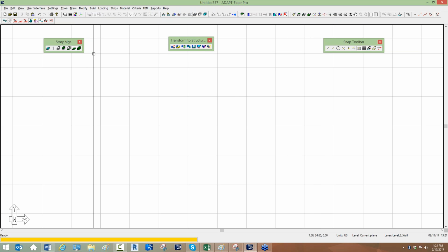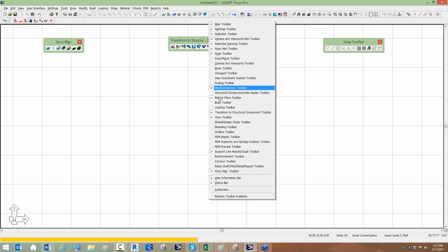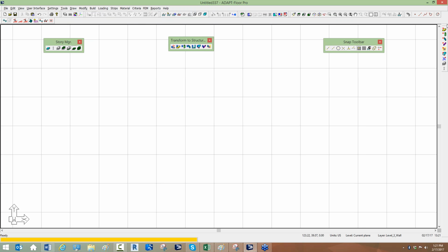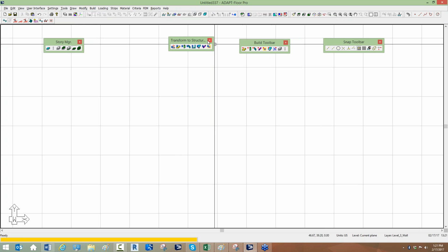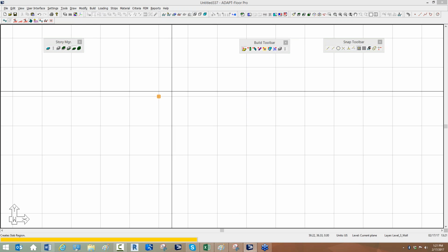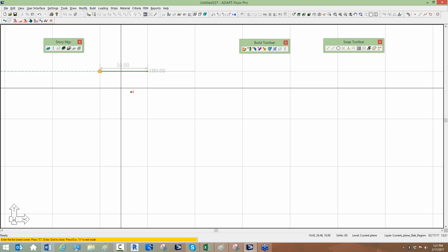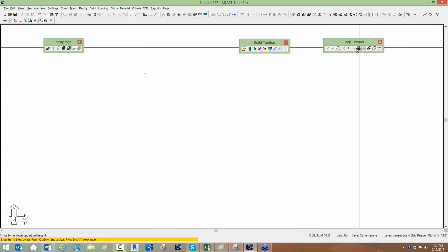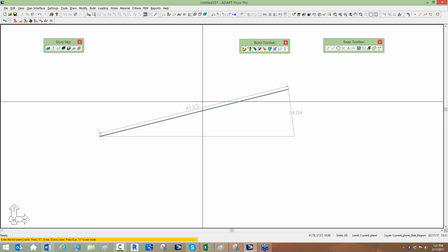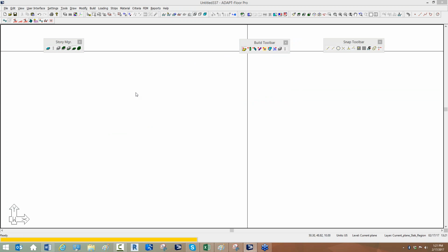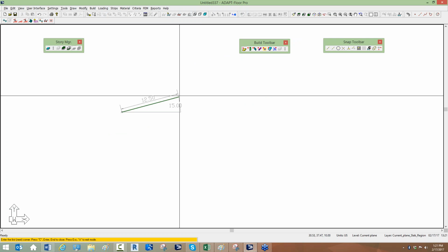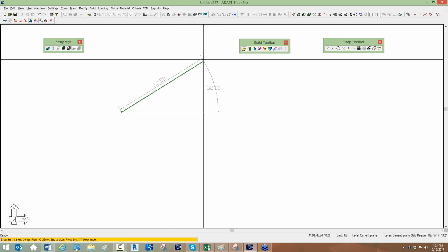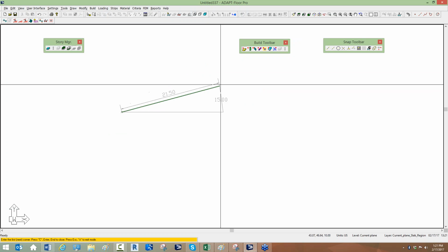And new to the program beginning Monday, build 2, as I mentioned, is if I build a model, and I'll use my build toolbar now instead of my transform. Let's say I build a slab. You'll notice when I begin modeling, the program allows me to see these dimensions. Let me go back and try that again. So the program has some dynamic dimensioning similar to other modeling interfaces. We have a linear dimension and an angular dimension.